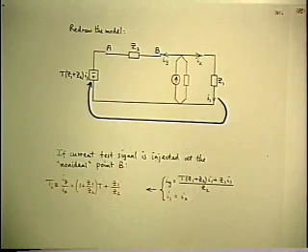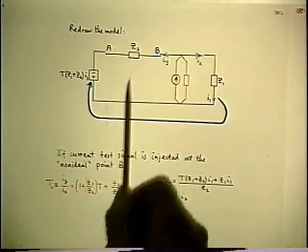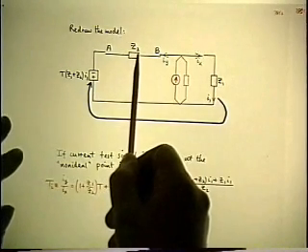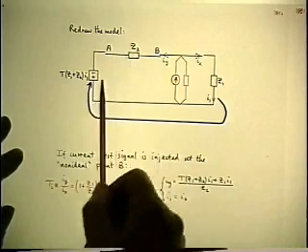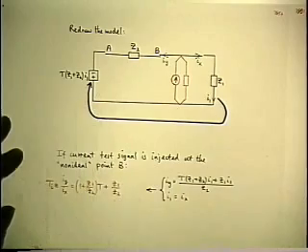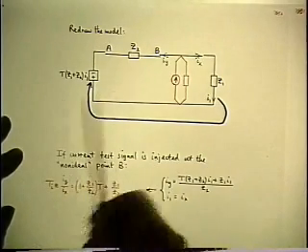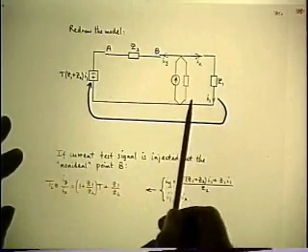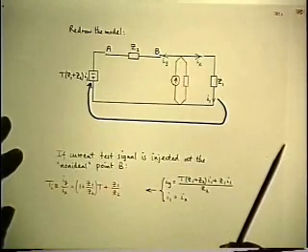Z1 over Z2 has to be small, which is the same thing as saying that the Z2 has to be a very high impedance, meaning that this works when you have a current source and not a voltage source on the left-hand side, which we already know is the ideal case when you would use current injection anyway.